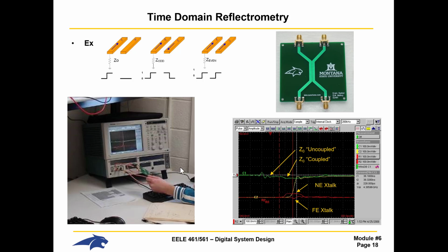All right. Then you connect another channel of the TDR to this guy, and you start driving in signals. So check out what happens here. The yellow right here, I'm driving into here. In this case, they didn't drive it. These waveforms are not for driving it. So what they did is they just observed on another channel of an oscilloscope, but they were able to look at the far end and the near end crosstalk. And that was with nothing being driven.